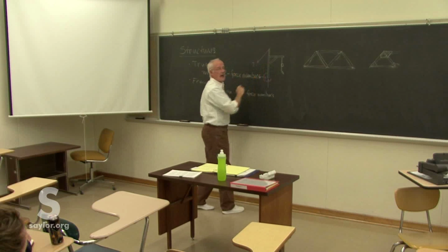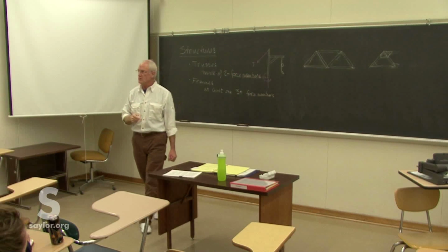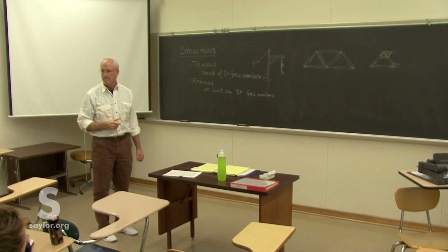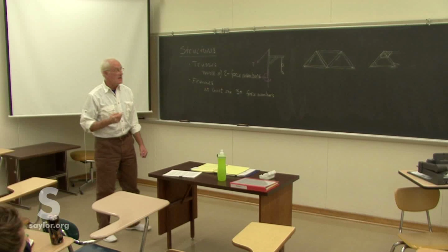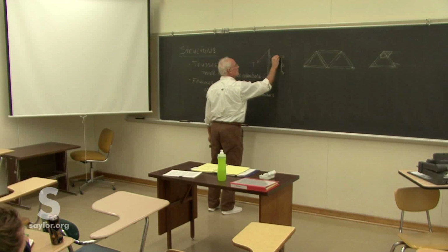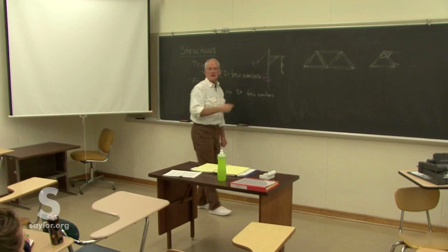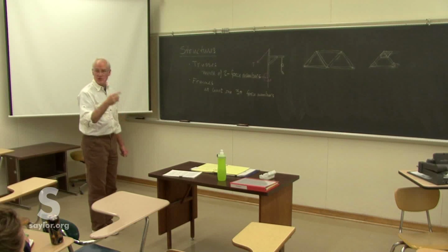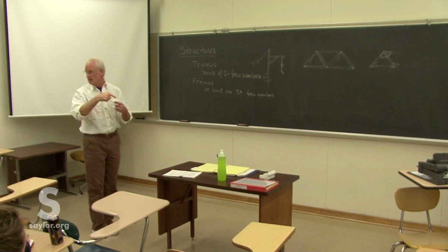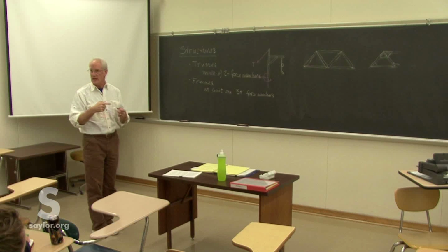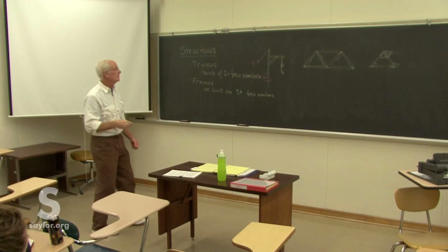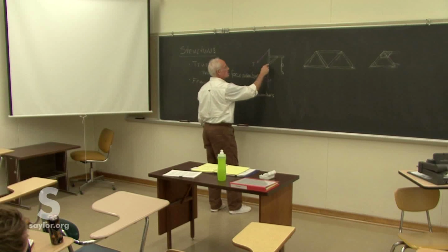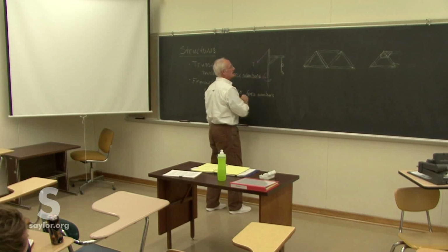This diagonal piece, is that a 2-force member or not? If the joints are pinned, yeah, that's a 2-force member. There's only 2 places any force could be applied to it. We don't count the XY components of a force as 2 different forces, because we can resolve those into a single force. So there's only a force at this end and a force at that end.